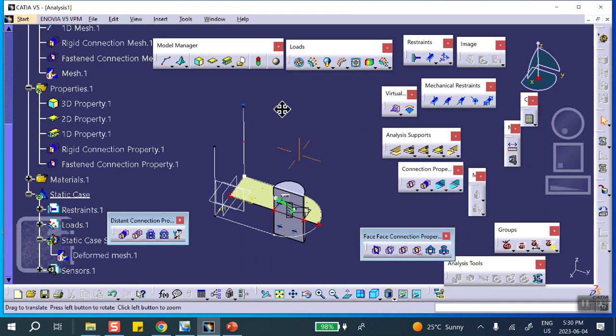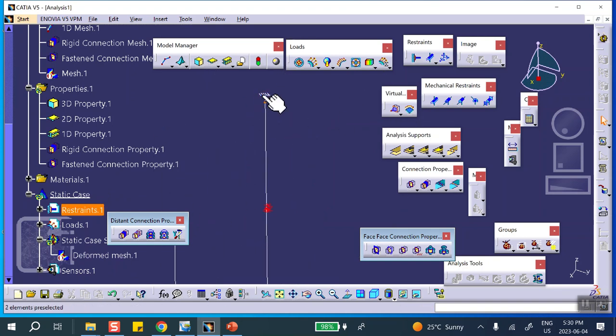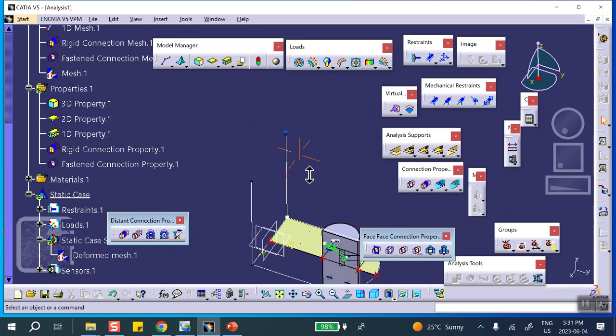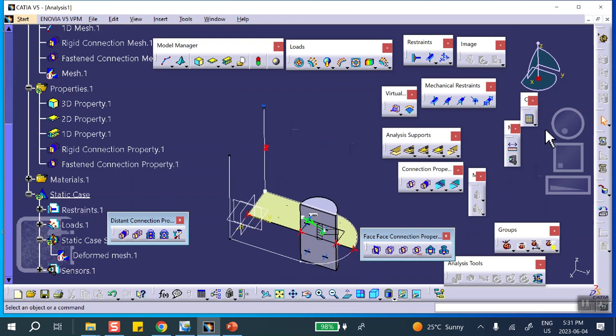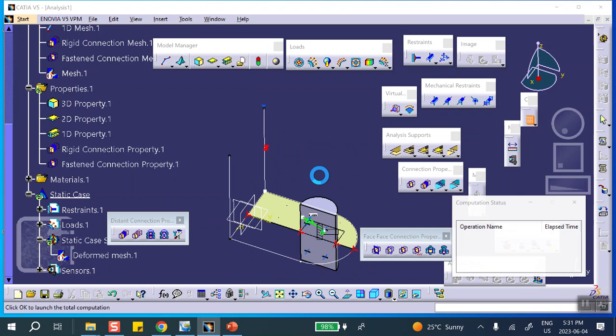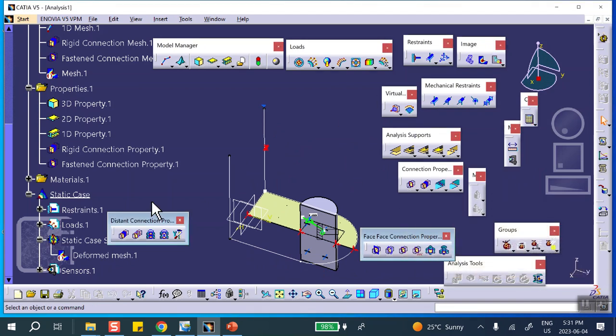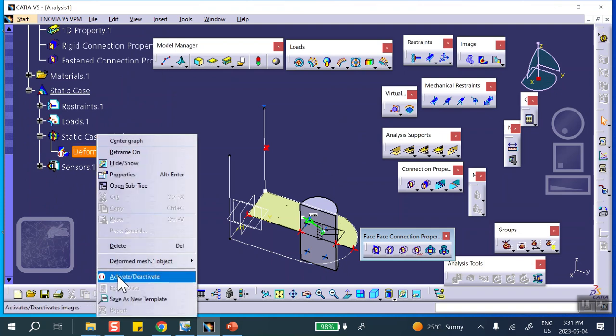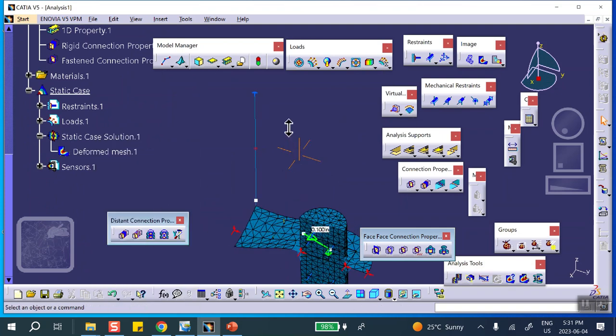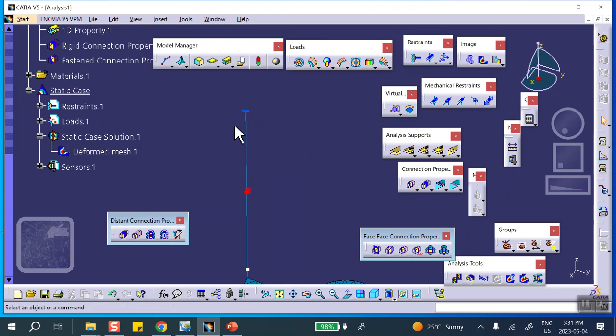And on the very top, if I run it now, it will work. But then what that means is on the top, it's not a cable anymore. It's kind of welded. Let's run it. You'll see. This will work. There's no problem. Yeah, we can see that. However, it's not right. Okay? On the top, there should be no restriction about rotation. Okay? This is why I made a finer mesh so that you could actually see it.